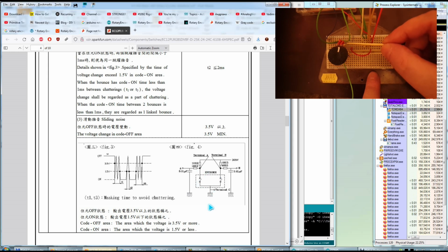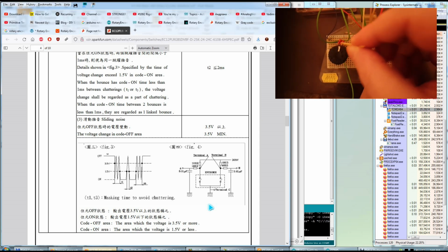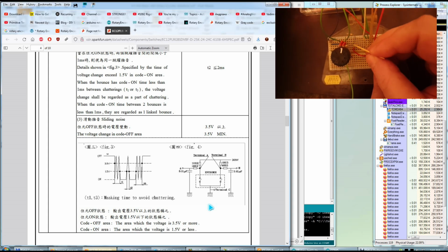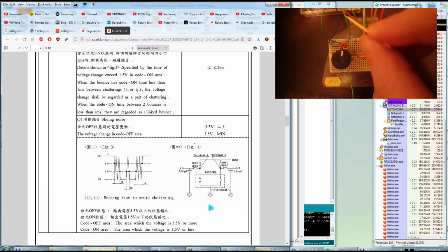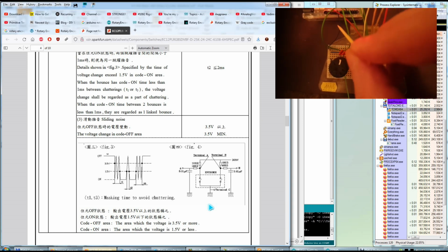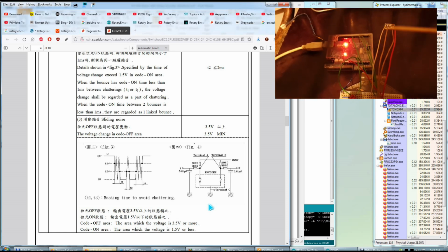And I'm having this resistor that you can barely see, but it's there. This is a resistor, and this one from that pin. In the middle is the zero rail. These two capacitors each have one leg on that zero rail, and here, these two resistors are coming from the A and B pins. Here together, both of them, at this point that you cannot see very well, but they are in the same hole, linked to this red line, which is going into the positive on the Arduino. And that's it. And these two lines are on A0 and A1. You see? A0 and A1 pins. And I'm having a wire for negative and another wire for 5 volts that I'm collecting from the Arduino board. That's it. And this is an RGB LED that I will talk about later.